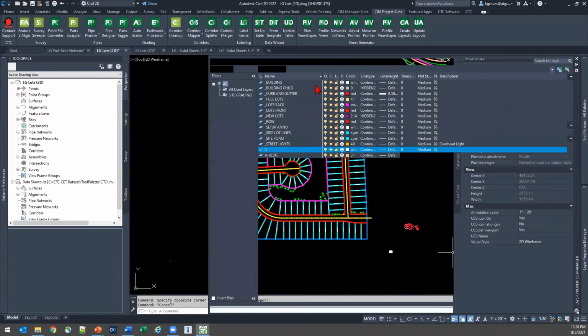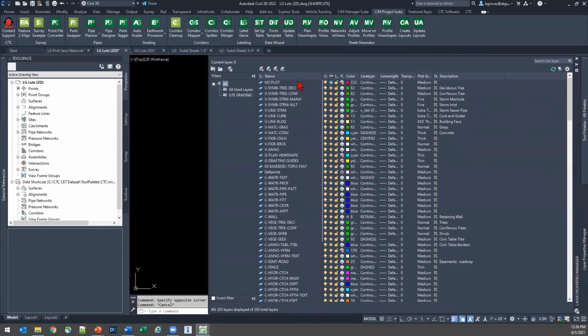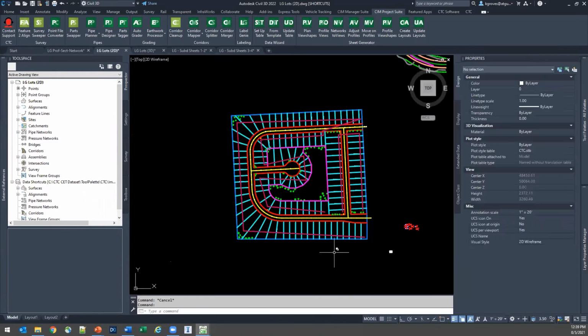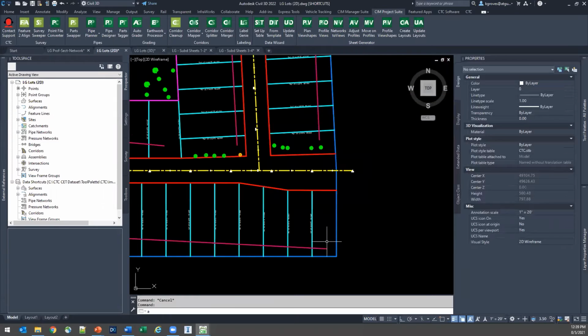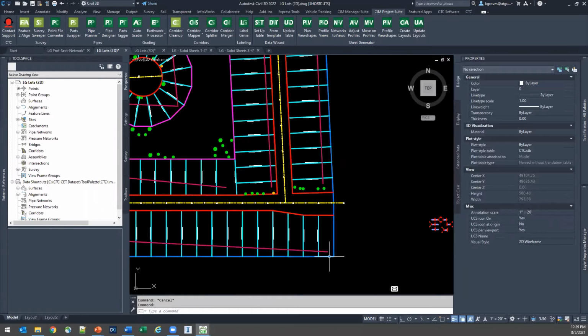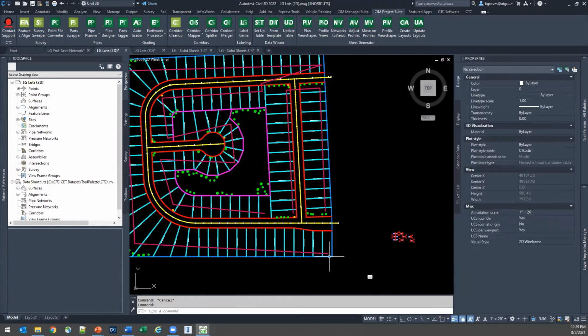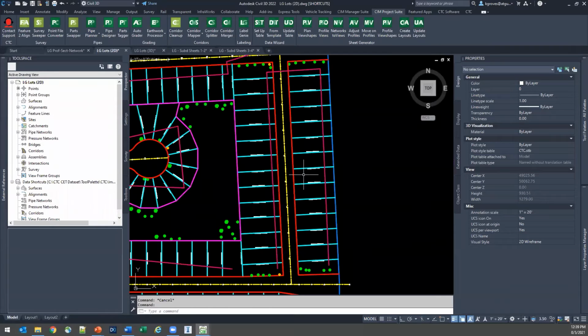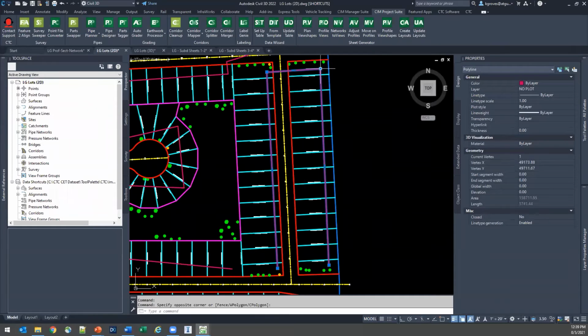Well, I actually have a layer in this drawing. It's my no plot layer, where I went through and I just drew a polyline. I made sure my start point was where I wanted it to be. So southeast corner is going to be lot number 1. We're going to go around, come in to the inside here, go around that cul-de-sac, and then these lots on the east side, they have their own separate polyline where we're going to go north to increase, east, and then we're going to increase back again toward the south.